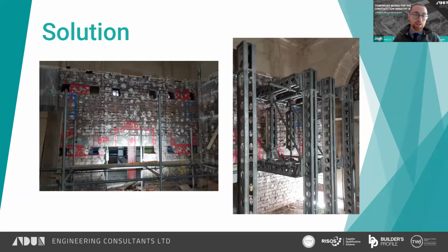Yeah, quite a neat solution on this particular part of the project, and it helped the project team out no end, because you can see some of the steel work on that photo on the left. You can see the lift shaft behind and some of the steel work going up, so it meant that these activities could be separated out. And that's the general common types of needling and propping that you'll see.